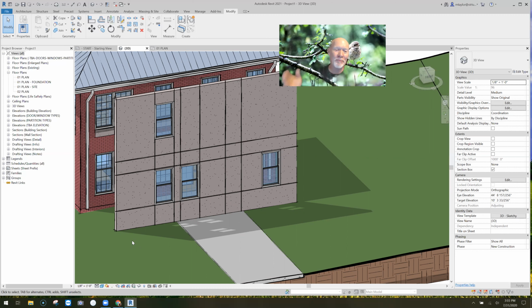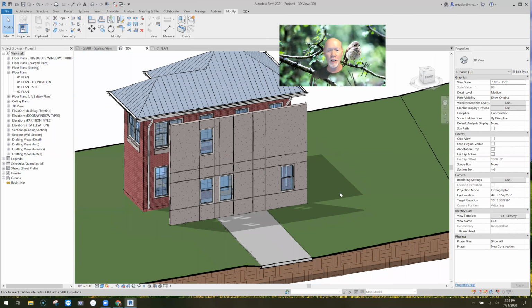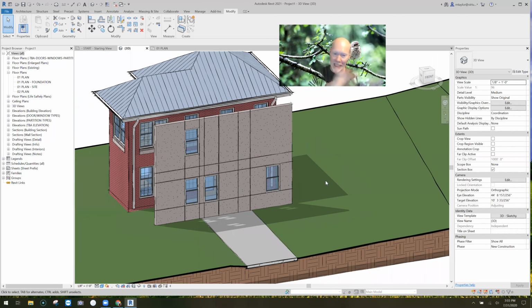Okay, what I want to do is show you guys that we did it. Go back and follow the instructions that I've done in this video and try to reproduce this. If you want your vertical and horizontal reveals in your project, then this is the way to do it. Put your horizontals into the wall type and then place and move your verticals. And you'll have your wall panels that are sectioned out like this, looking just how you want them. All right. I hope that helps you guys.